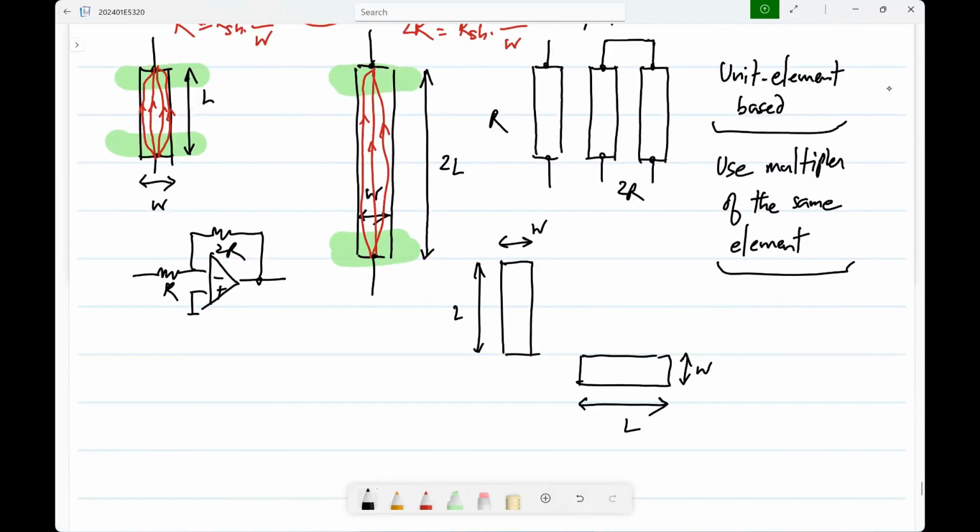By the way, one thing I didn't mention in IC design, again, these things will become more relevant when you do layout. Basically, everything is laid out in two directions. This is called Manhattan geometry because of the way streets are in the city of Manhattan. So you have only horizontal and vertical lines. You can have 45-degree lines in some cases, but everything is laid out like this. So this you don't do.